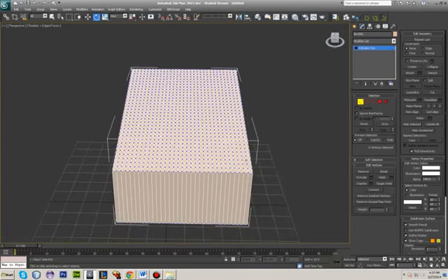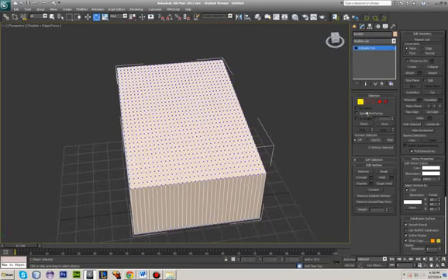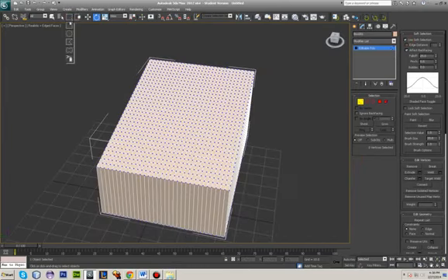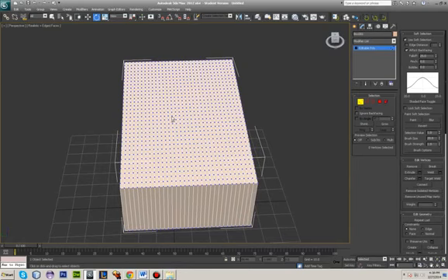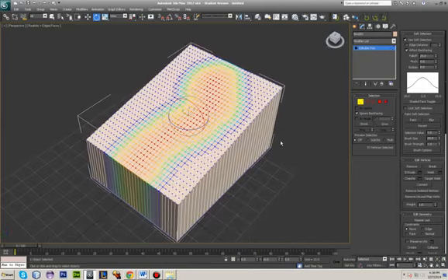Alright, then I actually want to cut out a little path, a little canal for the water to flow in. So I'm going to go to soft selection and use soft selection. Then I will switch my selection tools to the spray and going to ignore back facing. And let's see what I can do with this one. There you go. Play around with that a little bit.